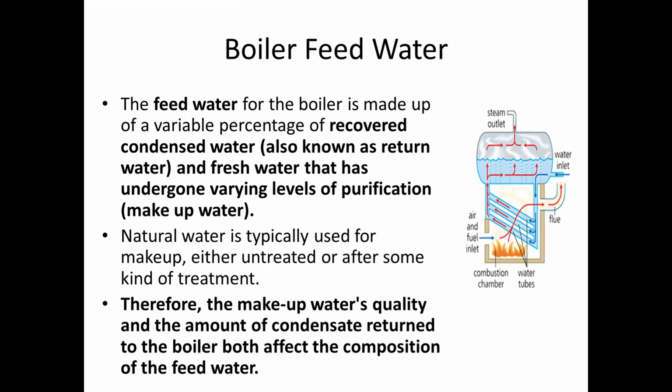But I would suggest that if you will be engineers someday in charge of this, you also need to treat your freshwater supply so that we have fewer problems along the way inside the boiler. Therefore, the makeup water's quality and the amount of condensate returned to the boiler affect the composition of the boiler feed water.